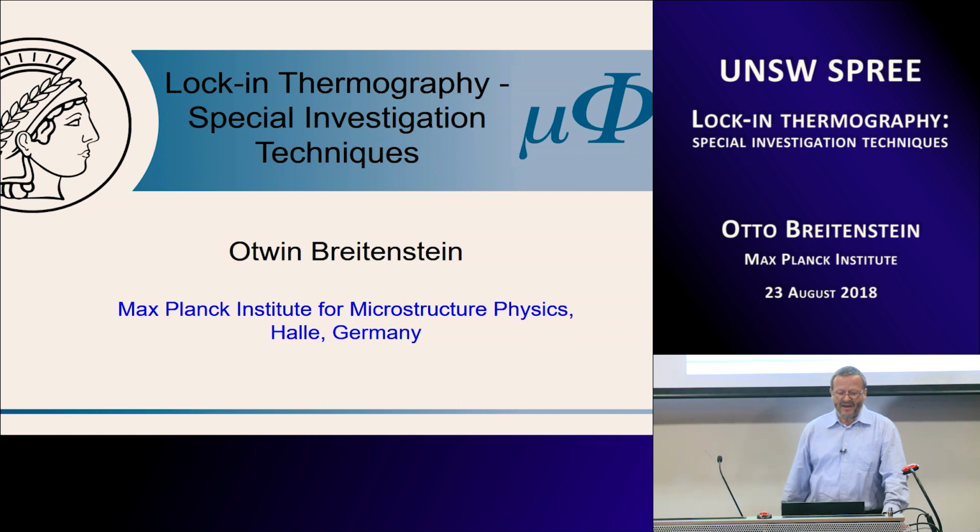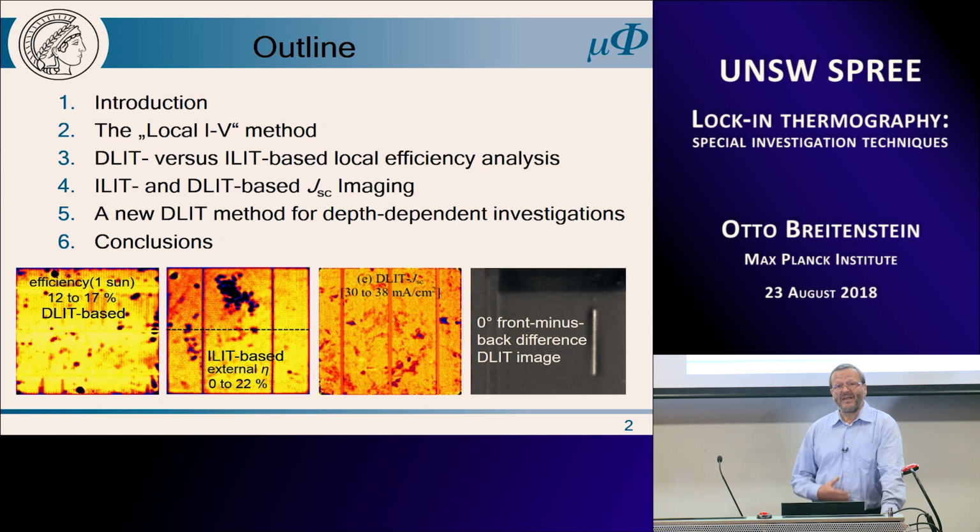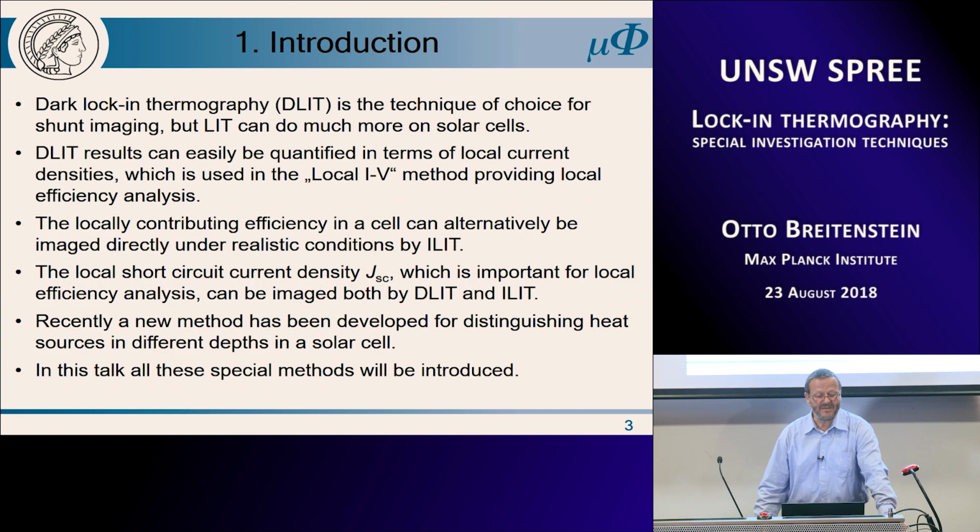So in this talk, after some introduction, I will go a little more into the details of the so-called local I-V method, which I have mentioned already in my first talk on inhomogeneities. Then I will report about illuminated lock-in thermography, so-called ILIT-based local efficiency analysis. Moreover, I will report about the possibility to image short-circuit current densities via lock-in thermography. There are two possible techniques, and I will introduce a new method for depth dependence investigations. This is a brand new result. At the bottom you will see some of the results which you're going to see in this talk.